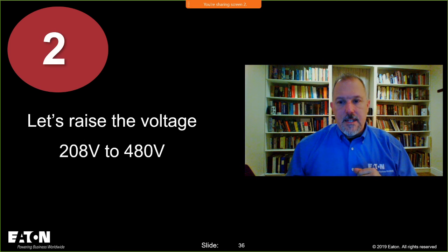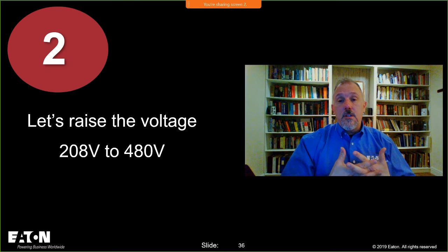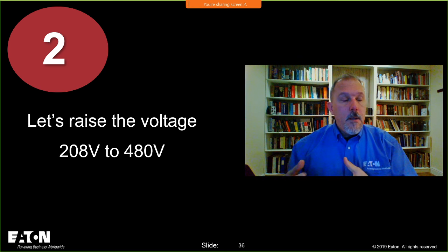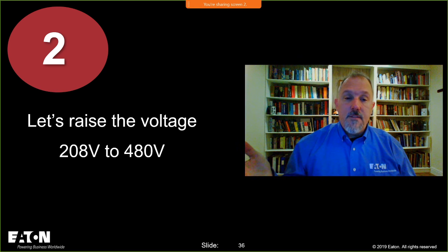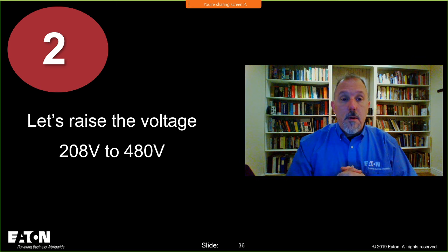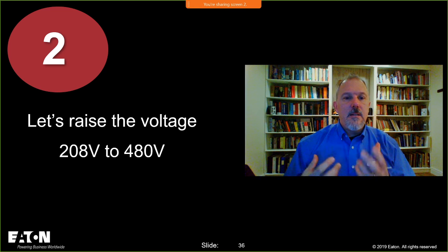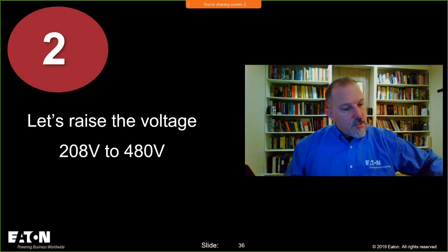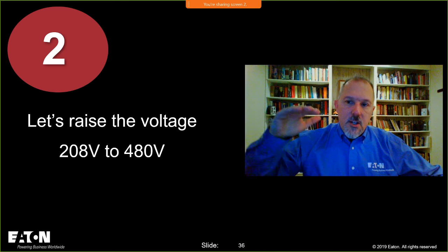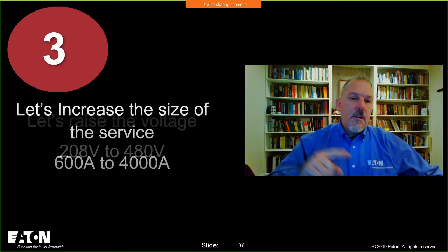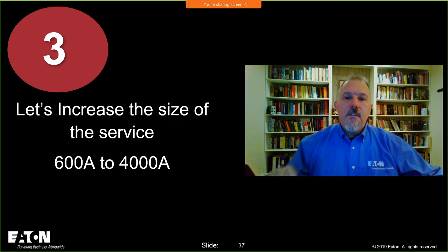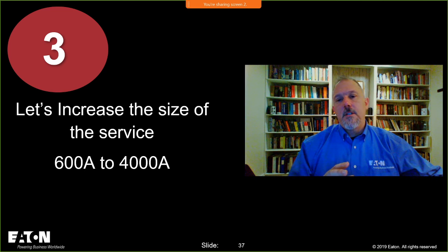The second thing they did was they said, we're going to increase the voltage from 208 to 480. I can distribute my voltage better. I can run 480 volt equipment instead of 208 volt equipment. These new products came on the market. They seemed to do a great job for this manufacturing facility, etc. So now we increased the voltage. And the third thing that we did was we went from a service of an average of 600 amps to 4,000 amps.